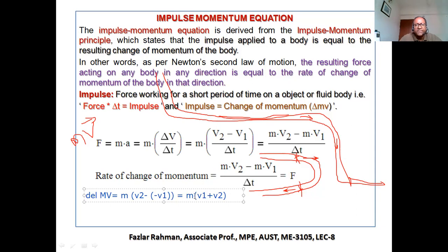So what are you getting? You see your momentum is changing, and due to this change of momentum there will be a force in the fluid, and the fluid will apply some force on your pipe. And that's why if you have an area where the change of momentum of the fluid inside the pipe is very high, that region you have to support strongly. If you don't support it strongly, then you will see breaking of the support of the pipe, or your pipe might break down.